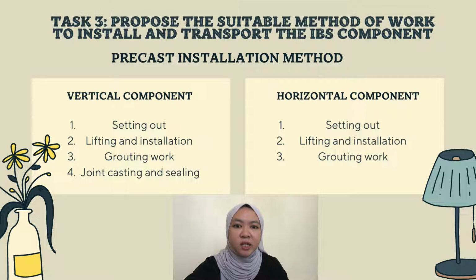The third one is grouting work. After inspecting the joint, use non-shrink mortar to cover the gaps along the bottom edge and the inner side of the panel to reduce the risk of cracking. Leave the installed panel alone for at least 24 hours. Lastly is joint casting and sealing. For the panel with cast in situ joint, the joint rebar should be correctly installed as required.